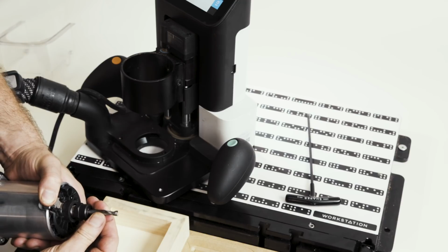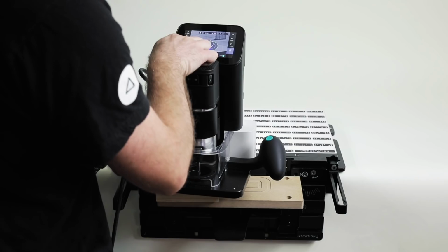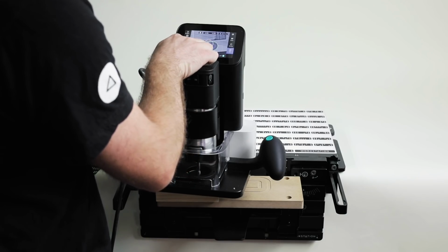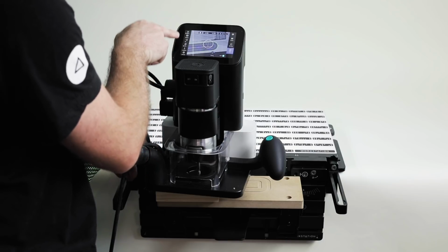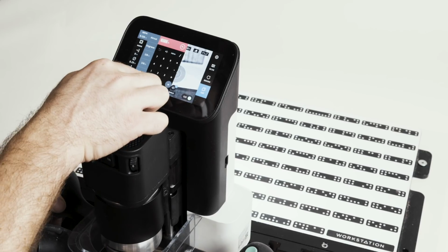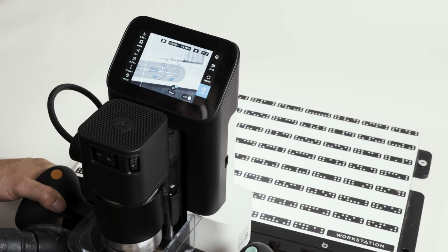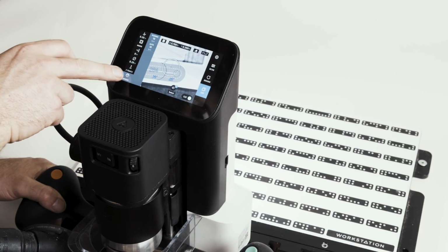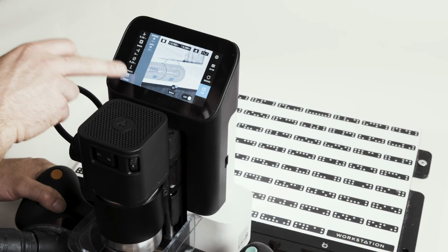So I'm going to put my cutter in and cut this out. Now it's just a matter of entering the relevant depths. So my cutter diameter is correct. My depth, I want 0.25, done. So I'm cutting to the right depth, right cutter diameter. We've done a Z-touch. Double check my speeds. We're good. Let's go.